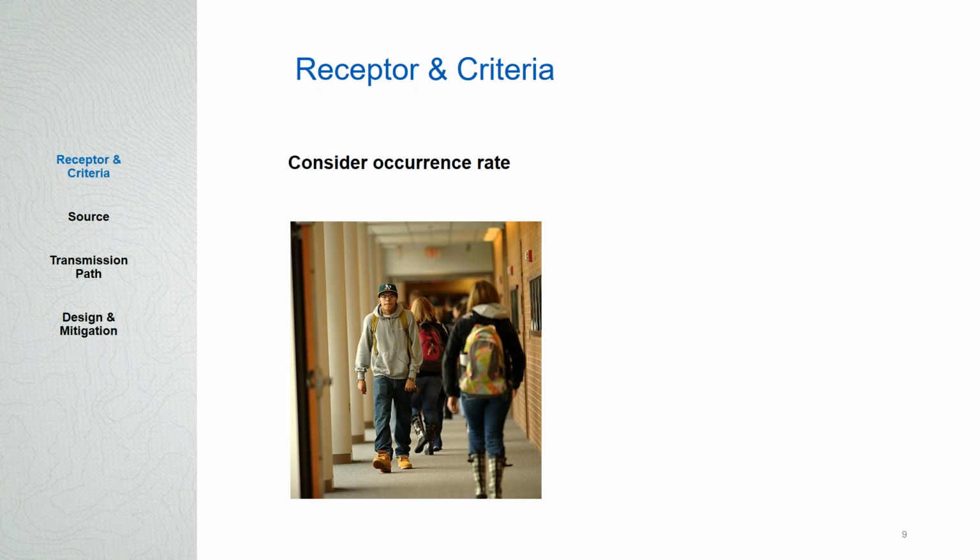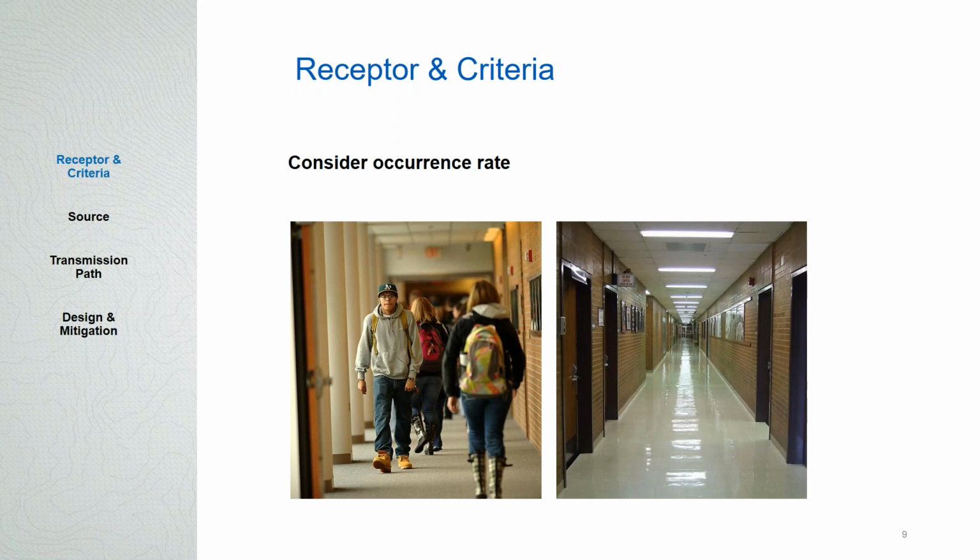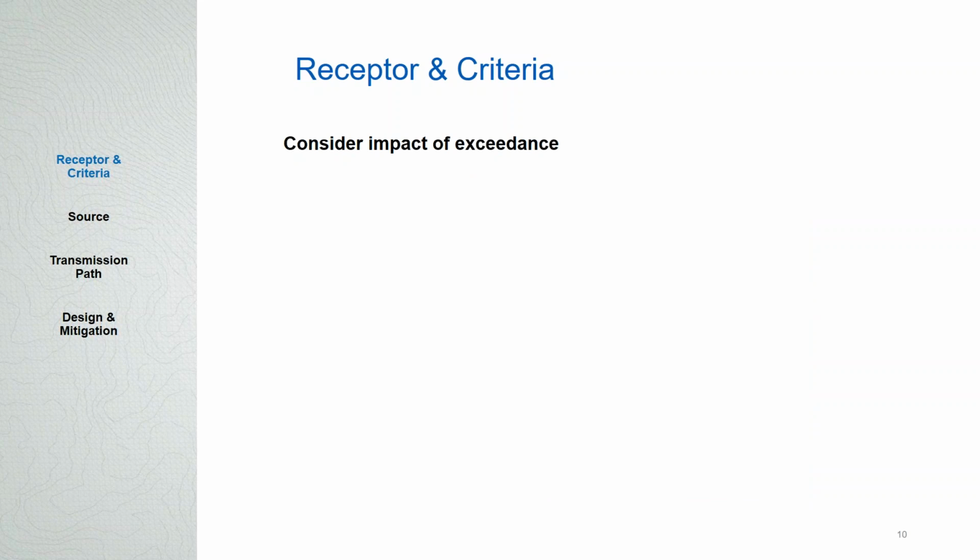Is that a problem? Versus maybe you didn't design your equipment so that you're quite going to meet the criteria under the worst case loading, but you're located somewhere off in a remote part of the building where there's never going to be anyone walking around. And if that's the case, when someone does walk by, it's so infrequent, is it going to affect the measurements? It's going to be so infrequent that you don't really care. You can just redo the measurement. Perhaps these are some things to consider, as how often might your worst case walking scenario occur.